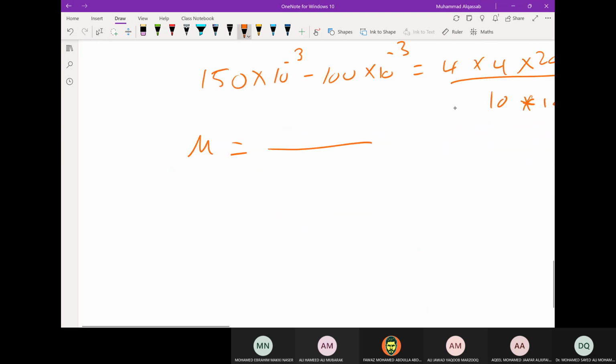And then for the second part, we have omega d equal to omega n equal to 2 pi over tau n. So the tau n is the time for 1 cycle. We multiply this by 4 because the question is to find the time for the 4 cycles. So t for 4 cycles is 4 times tau n.